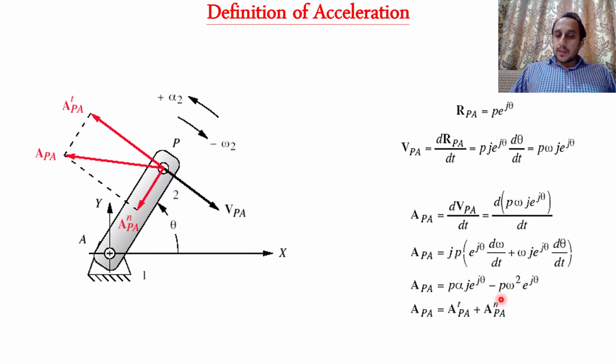अच्छा, सबसे पहले हम देखते हैं this normal component. ठीक है जी. अच्छा, नॉर्मल कंपोनेंट जो है, direction of this normal component of acceleration will always be 180 degree with respect to the position vector. पोजीशन वेक्टर की डायरेक्शन क्या? From A to P. ठीक है. और जो आपका सेंट्रीपिटल वेक्टर होगा या सेंट्रीपिटल एक्सेलरेशन होगी, that will be always 180 degree phase shifted from the vector of position. So that's why it will be directed towards the pivot. So this is the direction of normal component of acceleration.